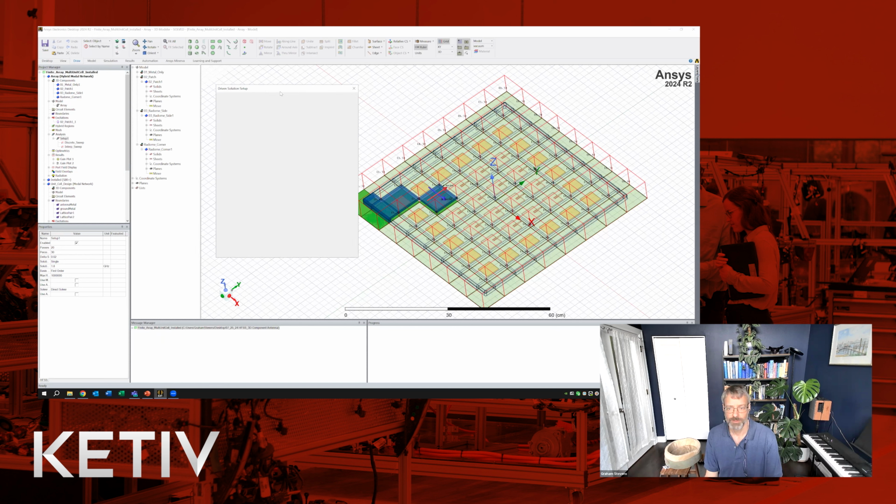In this particular case, you can also choose to use direct solver or domain decomposition, depending on how large your model is. You may want to play with both of these options to see which one runs faster for your particular model. Domain decomposition will tend to go much better for much larger stuff, clearly, but if you have something that's tractable within the direct solver, it can definitely be faster. So you want to explore that as well. And clicking on this skip 3D component array solve during adaptive passes can also speed things up.